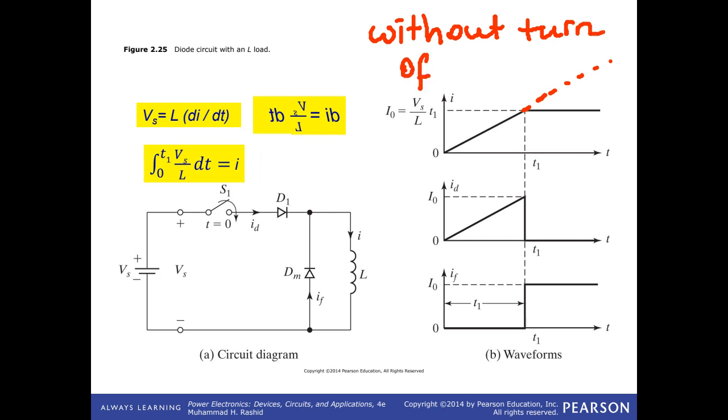Of course, it will burn down the transformer. If it is a transformer, for example, that's why people say don't give a DC current to a transformer. That is the reason. DC current rises and puts the transformer core in saturation and excessive current flows. But in power electronics, we switch it off.